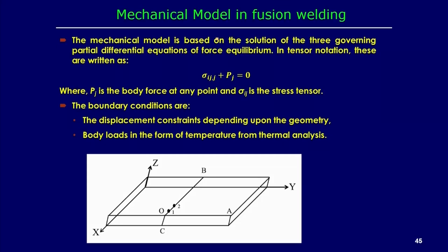Now, we will shift to the mechanical model, that means thermomechanical analysis, which is widely used in the welding process. Here, the mechanical model in the fusion welding process is sometimes called thermomechanical modeling. Of course, the mechanical model is based on the solution of the three governing partial differential equations of force equilibrium. In tensor notation, this is the governing equation, that means the stress tensor and the body force per unit volume make the equilibrium conditions, and if we solve these, we will be able to find the solution.